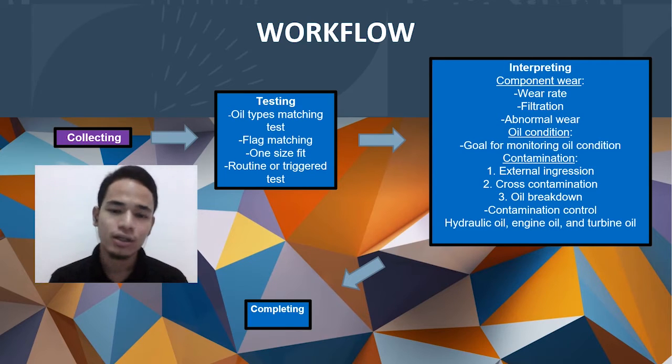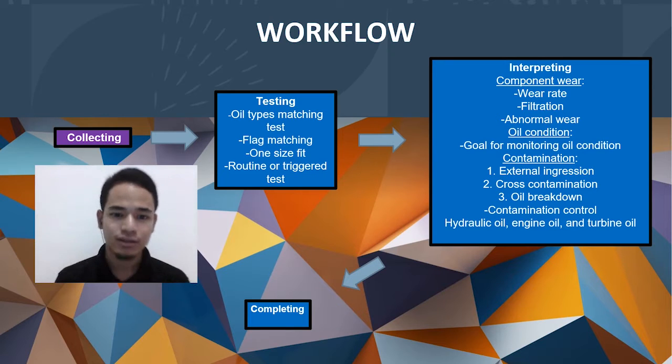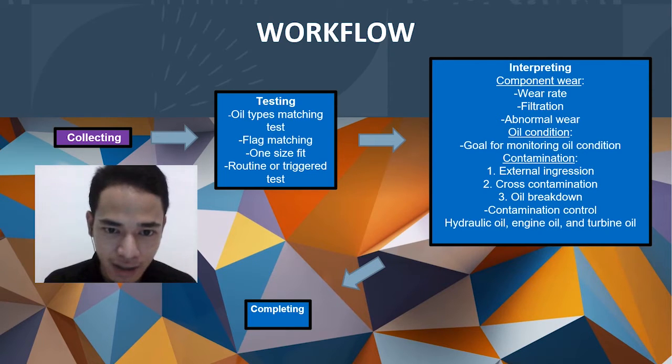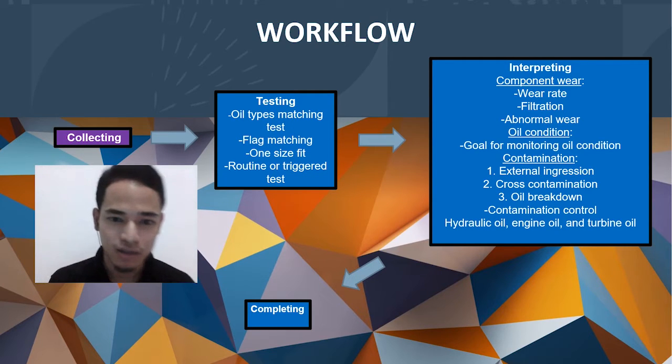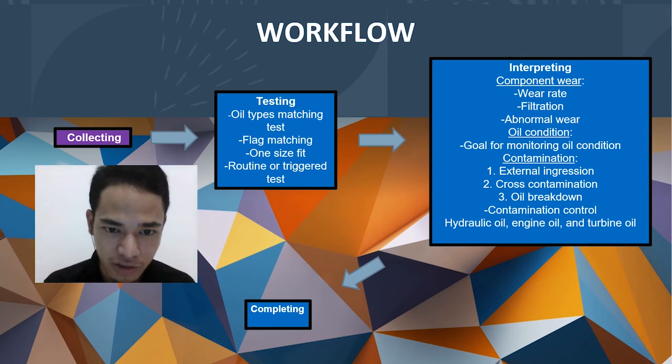Abnormal wear can usually be explained by, first, harsh operation. Second, ineffective maintenance. Third, poor oil condition. Fourth, excessive contamination. Fifth, mechanical issue. And the other thing is oil condition.